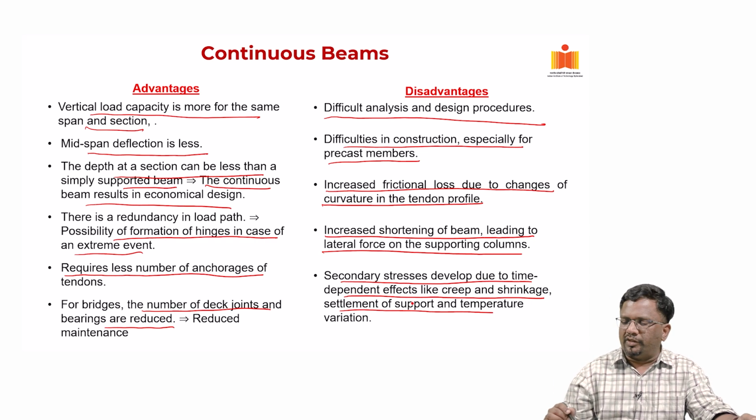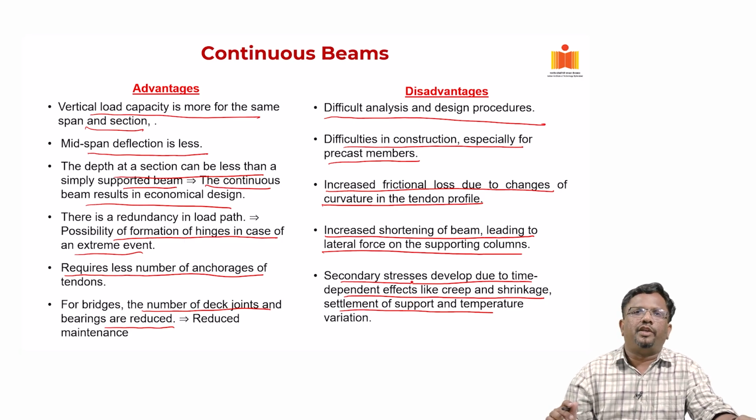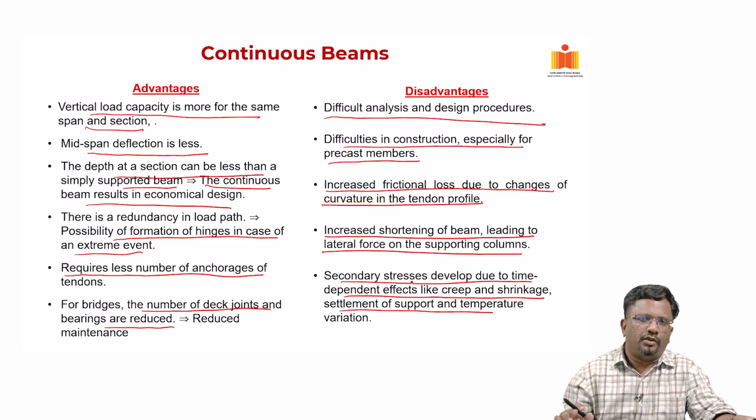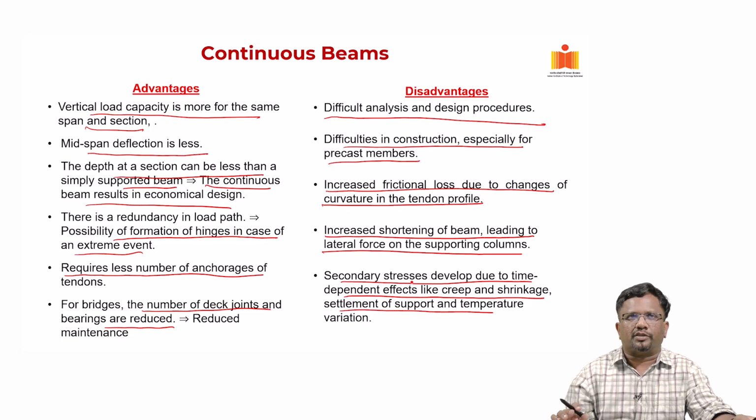So, all these things lead to more secondary stresses which are very difficult to estimate accurately. These are some of the disadvantages of going for a continuous system. Having said that, the advantages are much higher than the disadvantages. So, in modern-day construction, continuous systems are becoming more and more common.